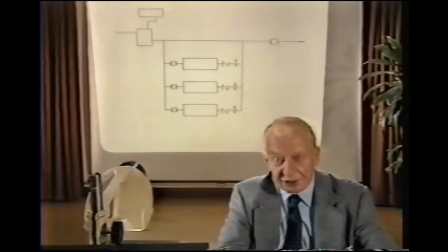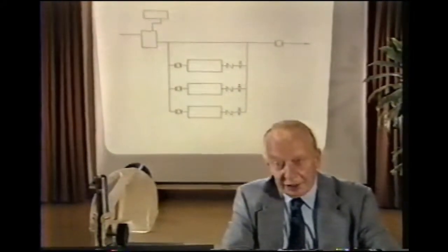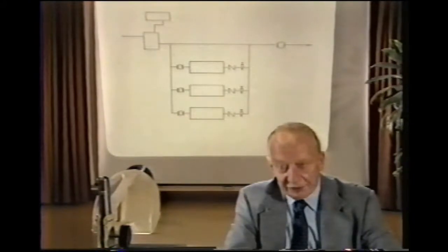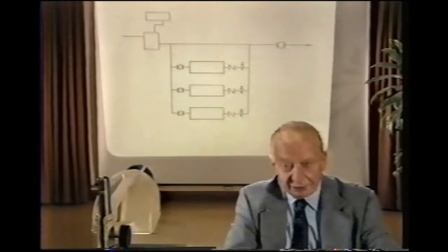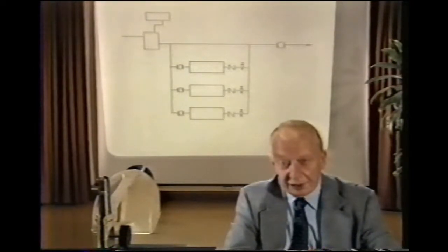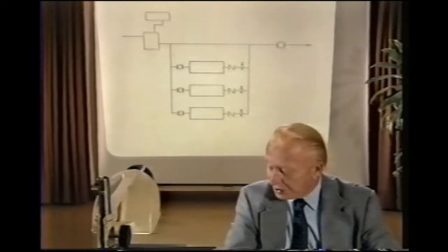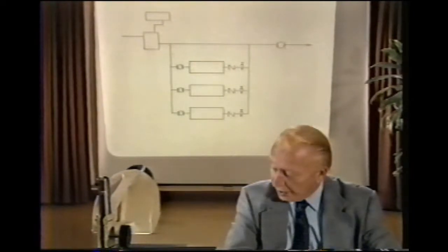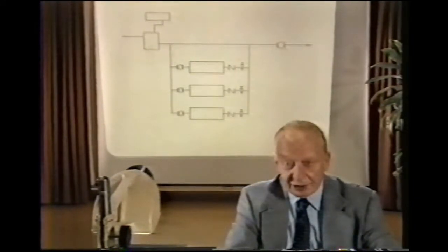Two-way control valves are also generally used in the crossover bridge in terms of modifying the flow rate through the primary circuit, primary distribution circuit, so that flow rate then through the chillers could vary unless these chillers are particularly adapted to a basically constant flow.